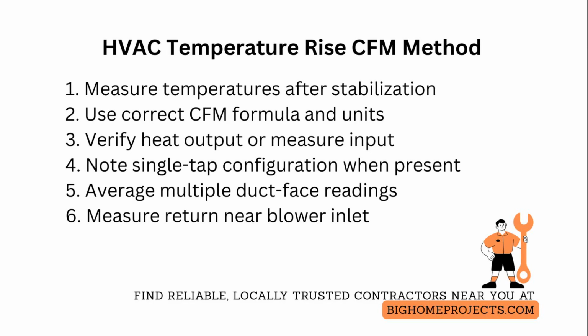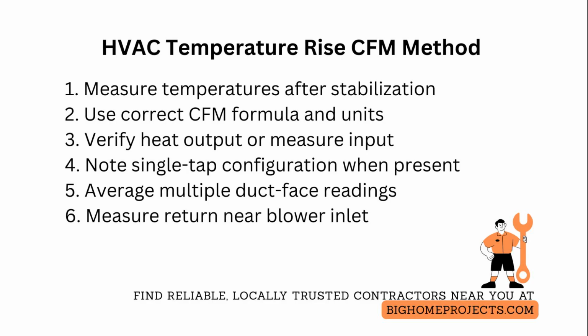Correct for return air mixing by measuring actual return temperature nearest the blower inlet, not a grill where stratification occurs, and if necessary, temporarily seal nearby doors to stabilize return conditions.